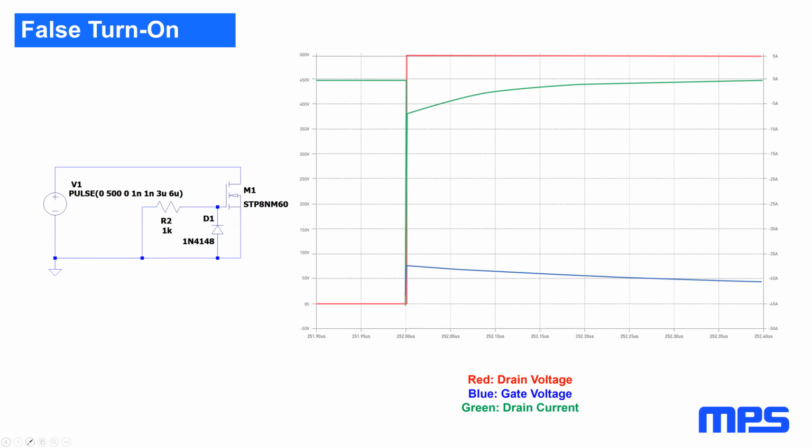To prevent this while still allowing for a slow turn on, a lot of gate driver ICs integrate something called a Miller clamp. That pulls the gate strongly to the source once the MOSFET's fully turned off, even if the resistance is higher during the transition to limit the slew rate.